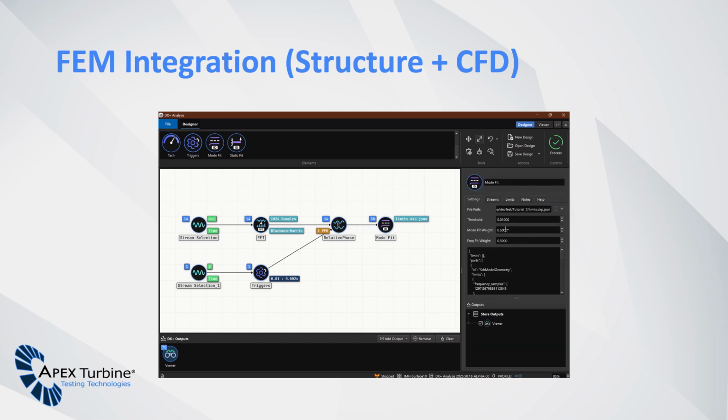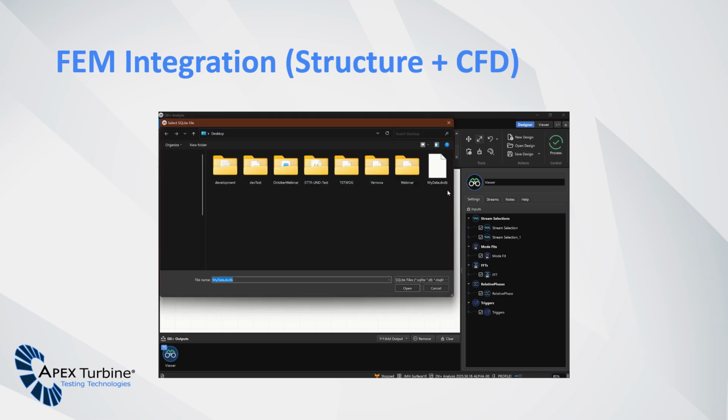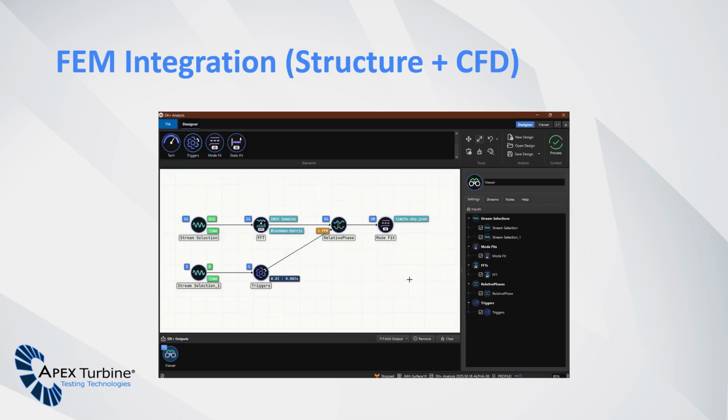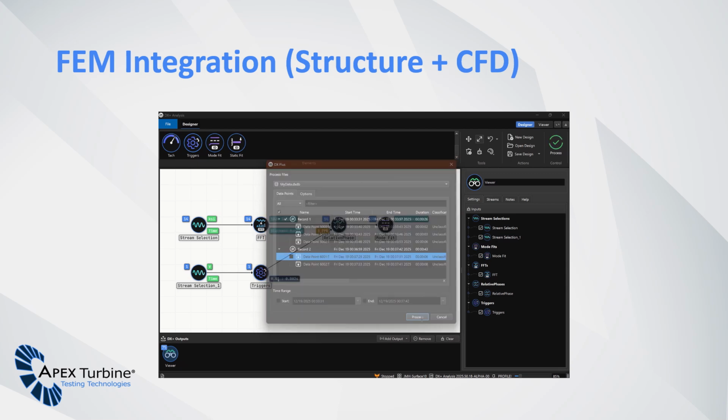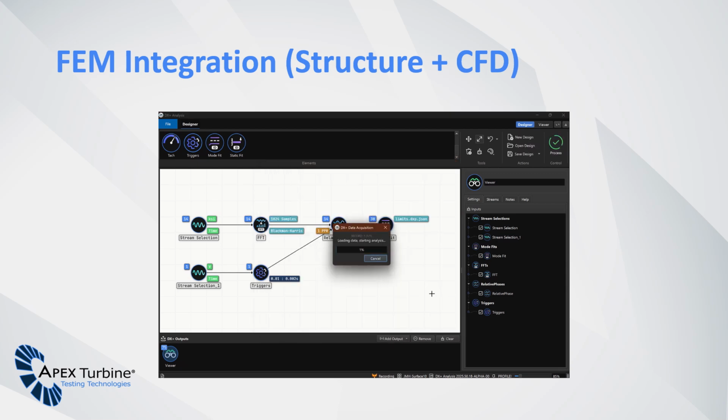After mapping sensors and their locations queried for results, these results can be exported to a file providing an analytical measurement vector. These measurements can be used by the mode and static fit processors for correlating the analytical with the measured. When doing so, the model can be used for visualizing the effects on the part given the data coming in. This visualization can also be time-synced with other data plots. This clip demonstrates this capability.